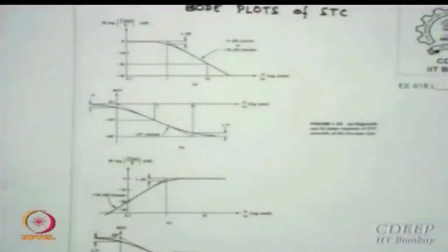And if you make tan inverse 10, which is close to infinite or much larger, it becomes closer to 90. So if your frequency goes from 0.1 to 1 to 10 times omega 0, the phase goes from 0 to minus 45 to minus 90, because of the minus tan inverse. So the slope down here is called 45 degrees per decade. Okay, that is the slope with which this will actually go down.